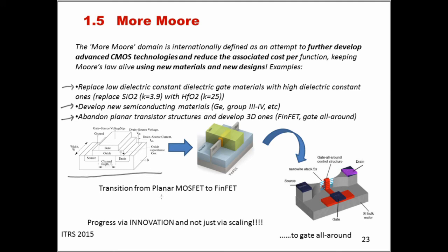So this is a planar configuration where the channel is in plane here, and move to a 3D configuration like this one, like the FinFET, where the body of the transistor, which is basically this part here, is actually a fin, and the gate is around it.